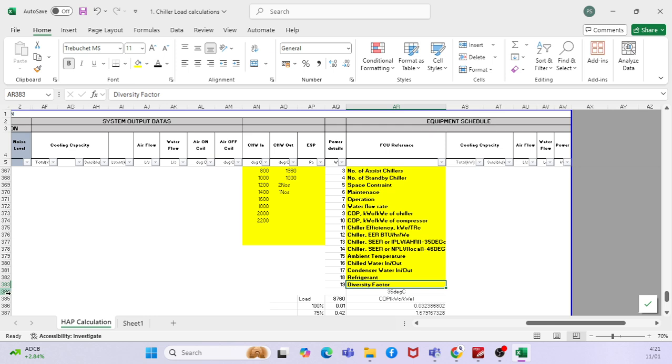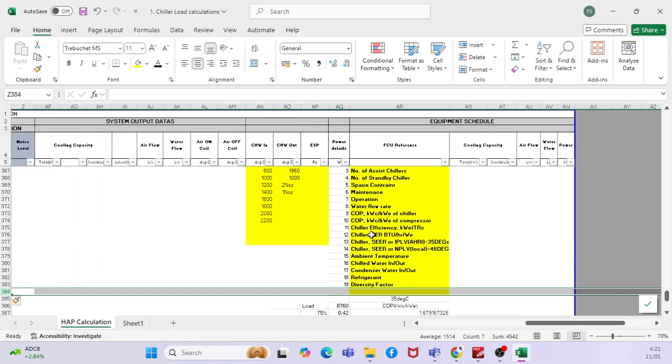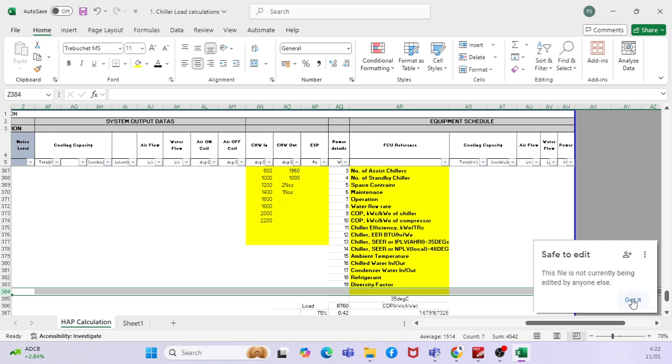And also, last time I told you that there is one more point which is very important. It's called elevation, right? So elevation is also very important when you do the chiller selections, because this elevation will also vary your chiller capacity, right? Say for example, because of the temperature, the air density.